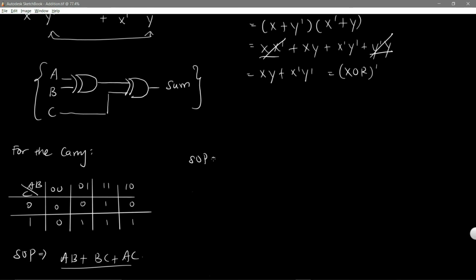So another useful step when we are doing Boolean algebra is that we can write something like this. So we can see this is an expression with 3 variables. So when the variables only use part of them, you can see that BC does not have the term of A. So you can actually express that as ABC plus A naught BC, right? This is equal to BC. This is one of the laws.